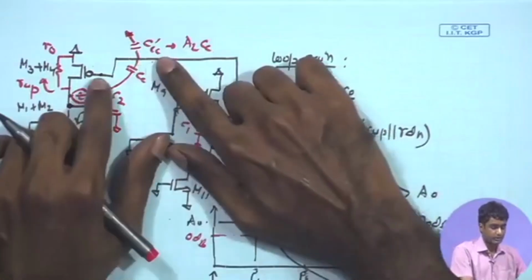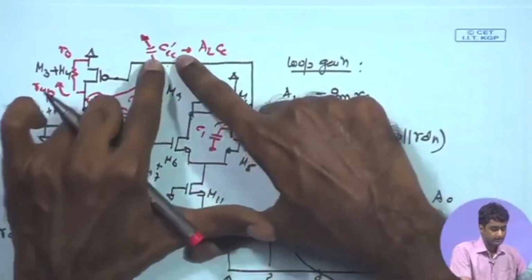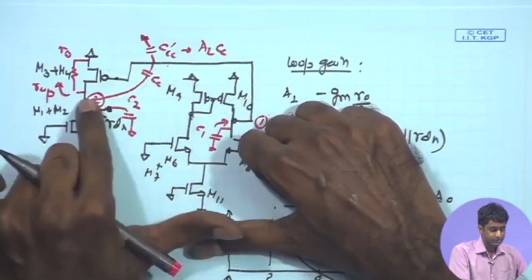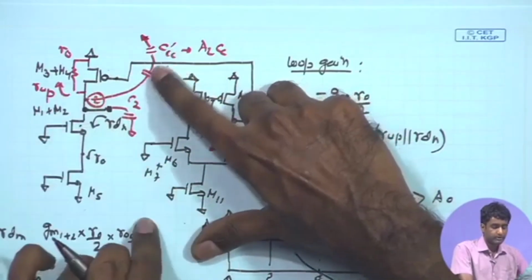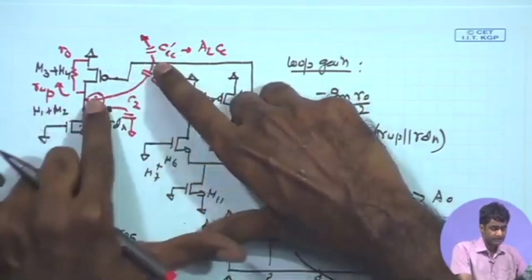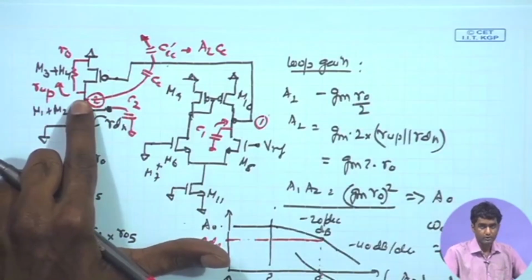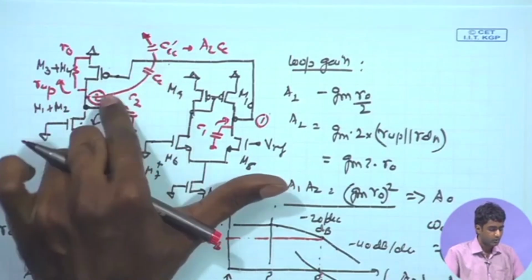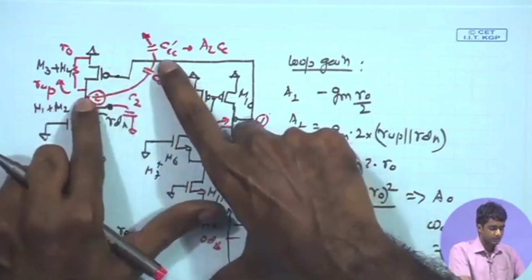As we will see in another example that we are going to take, a sufficiently large capacitor connected between the gate of the PMOS transistor and the output node produces a kind of low impedance path between the gate and the output at higher frequency, maybe close to P2, as a result of which the impedance looking into the output point becomes smaller.